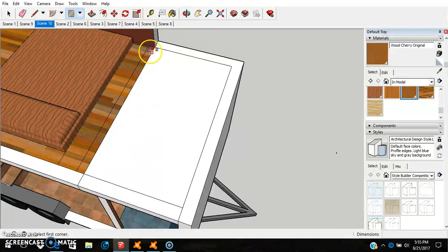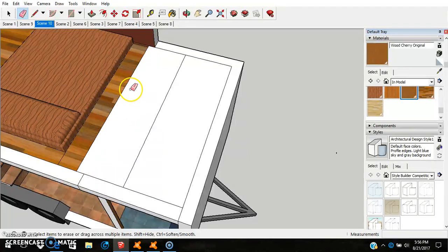Let's go ahead and press R, and we'll continue. We're going to add our cabinets, our furniture, our drawers, whatever we decide to put here. Let me do that again and enter the measurement. We're using a rectangle and going to make this 24 inches deep. We'll go from this edge, that corner, over to here. It looks pretty close to 2 feet, but we'll enter comma, 24, and erase this line.